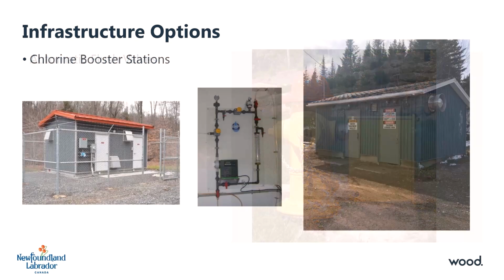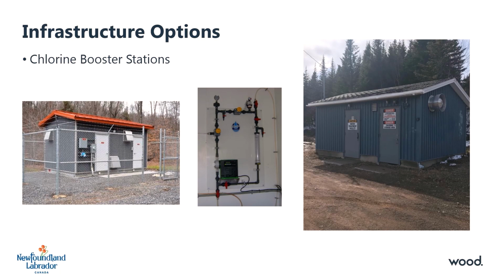issues come up. Another upgrade that could be considered is the addition of chlorine booster stations. Chlorine booster stations are used to inject additional chlorine into the water at a point within the distribution system. A chlorine booster station could be considered when chlorine residuals are low and cannot be adequately improved by increasing chlorine dosing at the beginning of the system. Additional chlorine would be added at the booster station to increase the amount of chlorine at the end of the